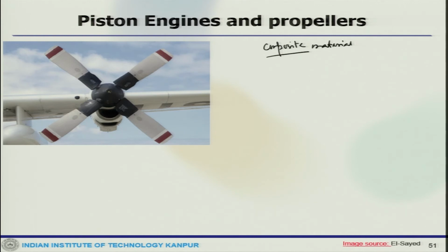Now, we can think about control. There could be fixed pitch, which is used for small aircraft, where blades are fixed at a certain angle to the hub, which usually never changes, but can be altered on the ground only, not during flight. The Wright brothers were the first successful developers of such fixed pitch propellers.